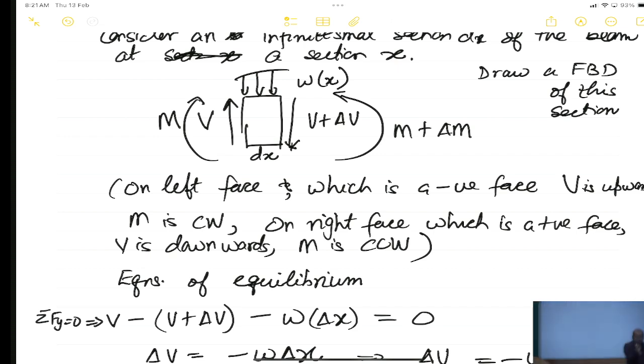See, this is an infinitesimal length. D of W will become a second differential. See, W at x is equal to 0 at x, and then it keeps on increasing, so it becomes second order. That is why you take it as infinitesimal length and you say the average is W, so W times delta x. So, W in some sense represents the average W from x to x plus delta x, and in the limit delta x goes to 0, it becomes W.